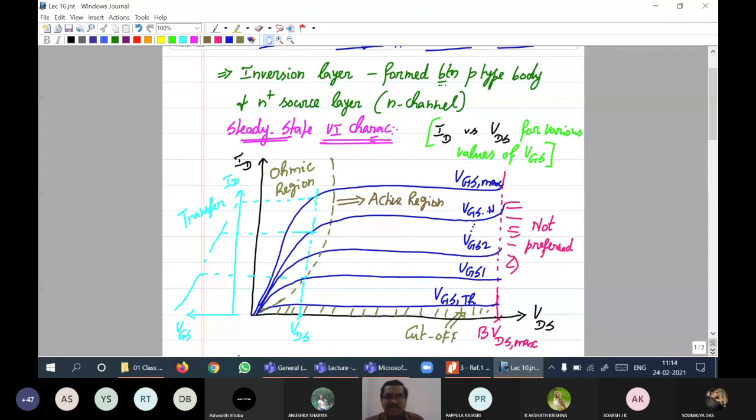In the previous session I had mentioned that the drain source ohmic resistance will be slightly more than the power BJT, and I remember to have noted down 3 MOSFET devices whose on-state resistances were 5 milliohm, 6 milliohm, 10 milliohm, etc. So that resistance multiplied by drain current will give the on-state voltage drop. Only that is going to be present across the drain and source during turn on.